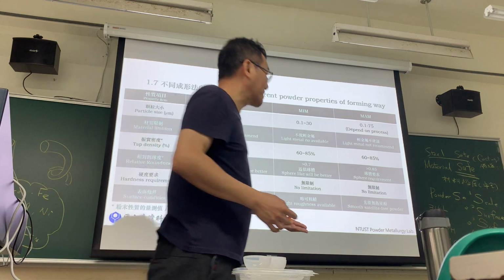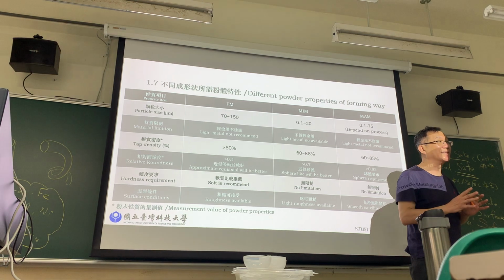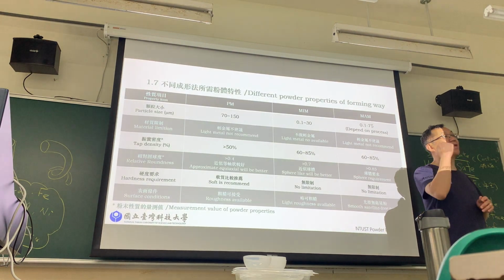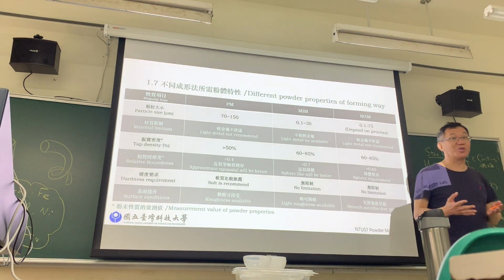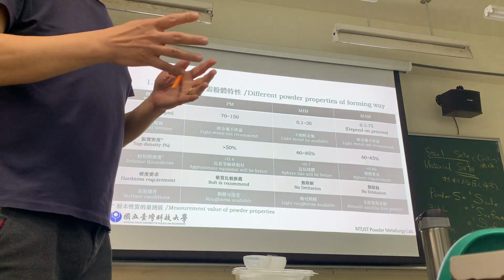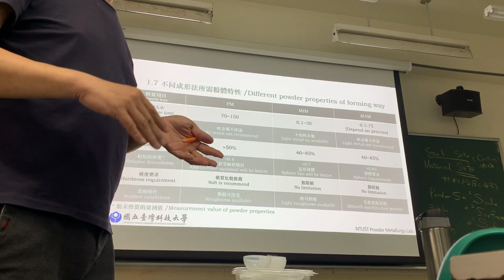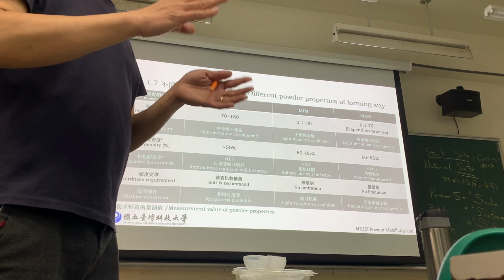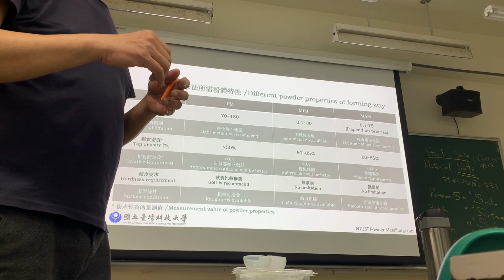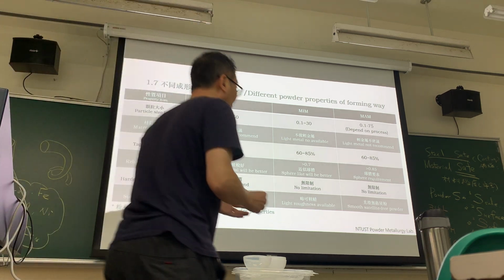Why? Because aluminum material in water will produce hydrogen. So it exploded again. So please, you should understand which kind of powder. If it's powder, just use one kind of material to make this, for safety. Don't use water. Use the other, or sand, or use salt to reduce the temperature. It's much better.